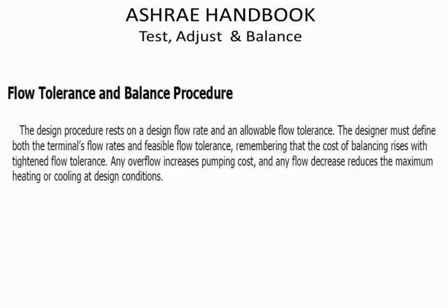Now, it's interesting if you look at the ASHRAE handbook, Testing, Adjusting, and Balancing, they kind of emphasize this, referring to the cost of balancing rising with tightened flow tolerance. So yeah, we could put a very expensive balancing valve in there with a small flow tolerance, but you can see you're going to have really diminishing returns in doing so.